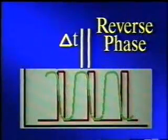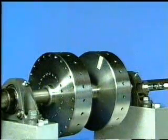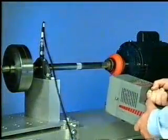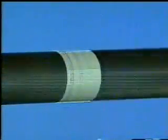All CSI equipment uses the true phase convention. When balancing, you will need to know which convention your system uses so that correction weights will be located correctly. But for most general phase measurements, it is not necessary. Other tools that can be used for making phase measurements are a strobe light and a vibration sensor.